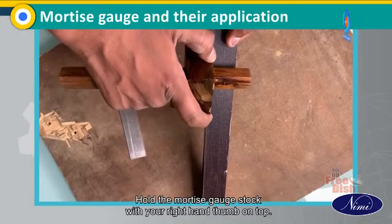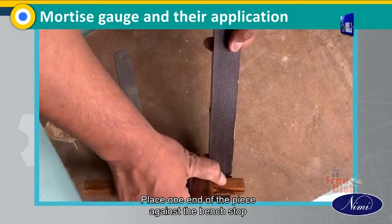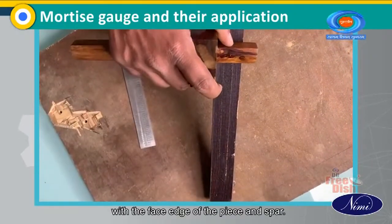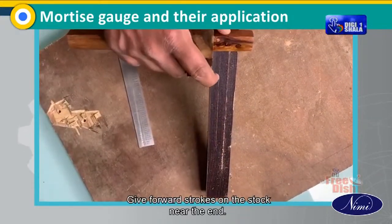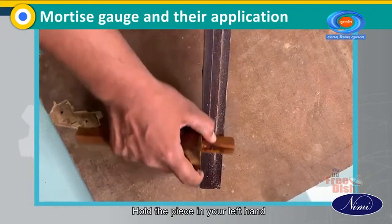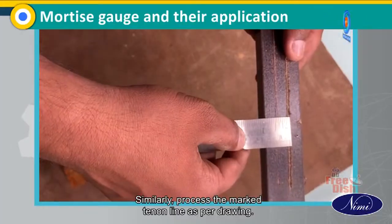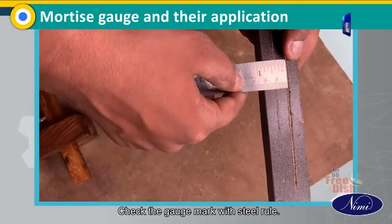Hold the Mortise gauge stock with your right hand thumb on top. Place one end of the piece against the bench top and the other end in the left palm. Place gauge stock in contact with the face edge of the piece and spur touching the piece lightly in slanting position. Give forward strokes on the stock near the end. Hold the piece in your left hand and complete the gauge marking parallel lines of tenons. Similarly, process the marked tenon line as per drawing. Check the gauge mark with steel rule.